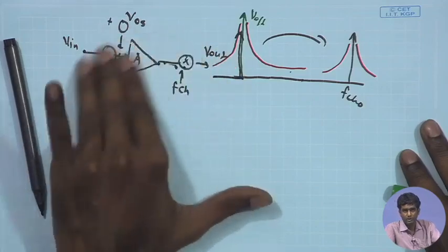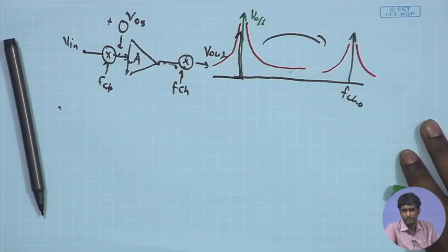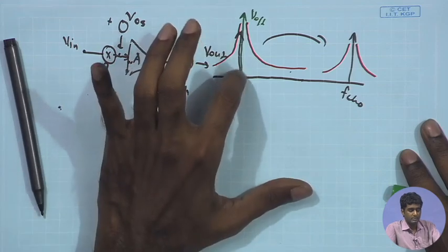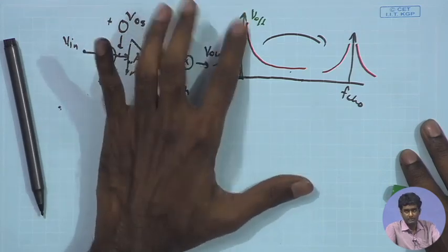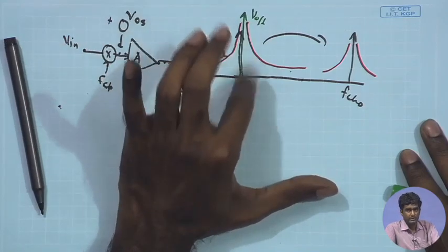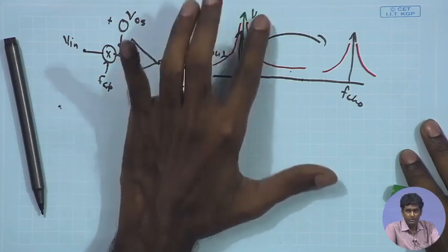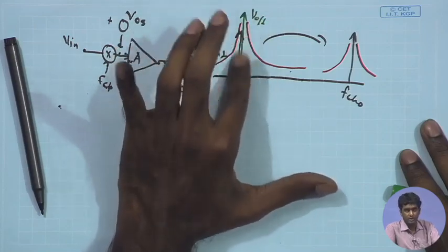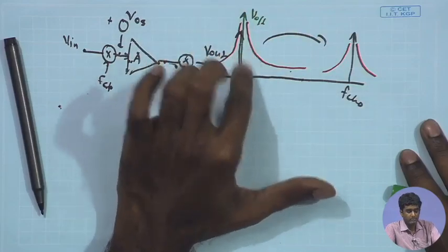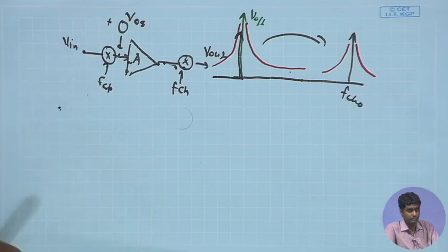So, the chopping also takes care of the offset signal, it is allowing separation of the offset from the low frequency DC signal. Of course, in our case we are not concerned with the DC level of the signal, we are anyway trying to reject the low frequency content, because you are having noise etc., and dynamic offset that we will see just now. But in case of the overall transfer function, it may be important to consider that the offset signal also gets shifted to high frequency because of the chopping operation.